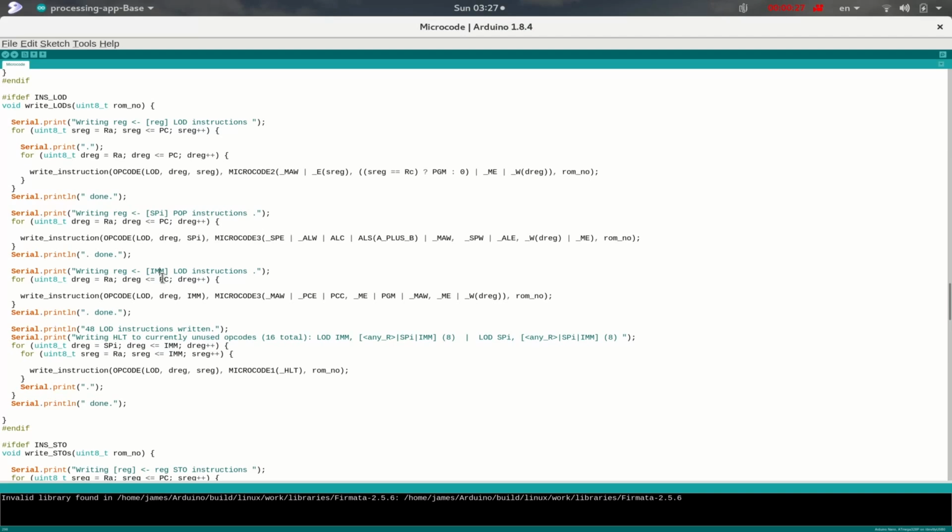So what we need to do is first go and get the address in program memory, then load that address into the memory address register, and then finally read out data memory into the destination register. As we can probably guess, that will be an operation that requires 3 steps of custom microcode. And so the very first thing we need to do is dereference the program counter.